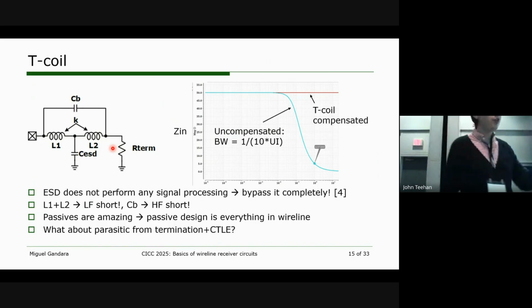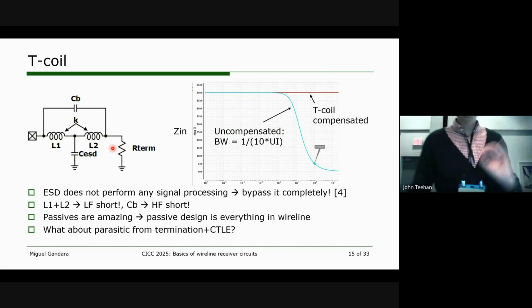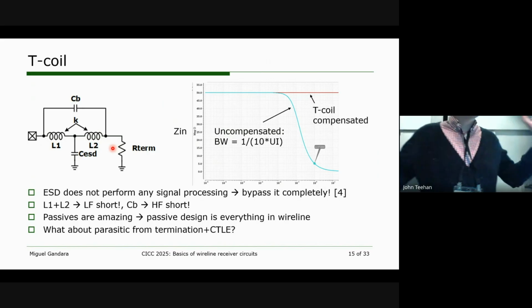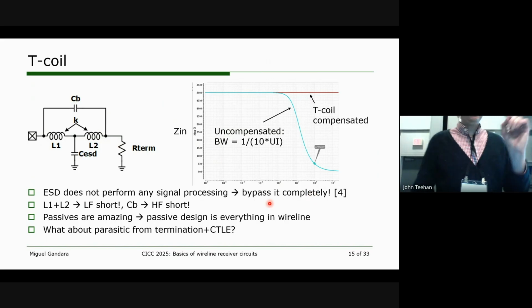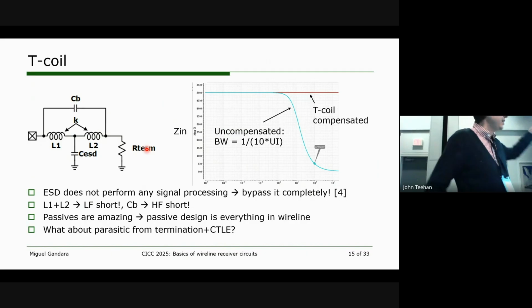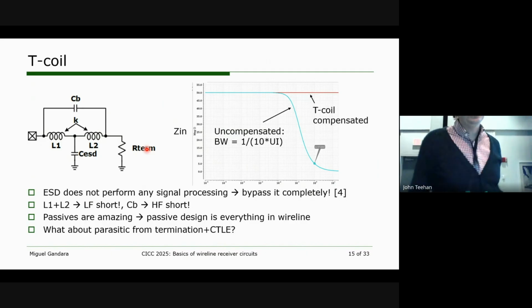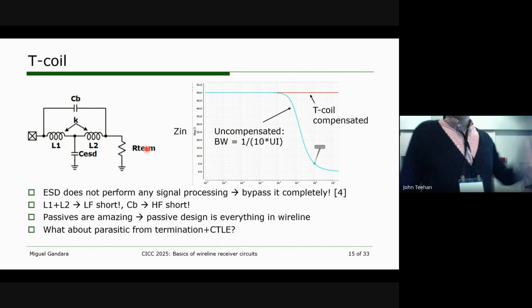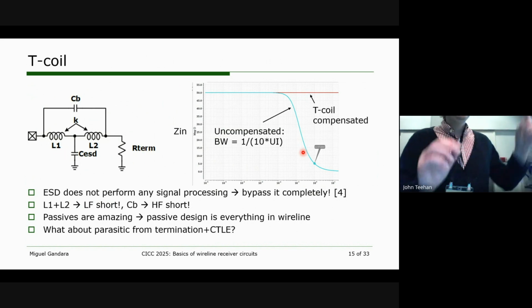So actually across all frequencies, you have to be very careful when you design this, but anyone can build this. You can build this yourself if you want to. You can look at this reference, take any RC value you want. In my case, I have the 8 gigahertz bandwidth. You can take 10 gigahertz bandwidth, whatever bandwidth you want. Build this passive network, and then there's a huge list of design equations that reference 4 gives you.